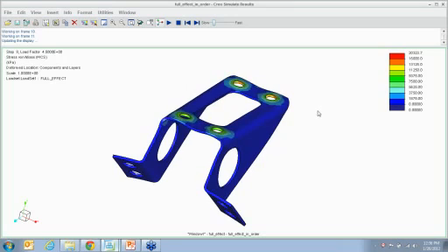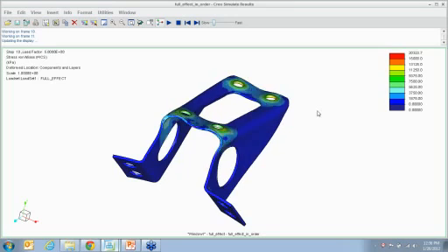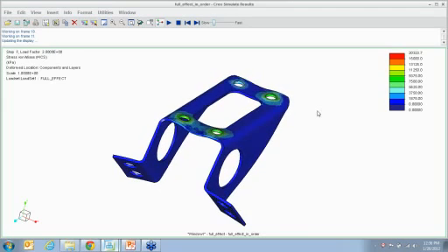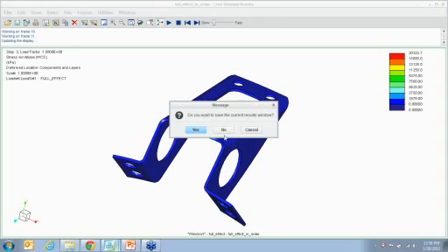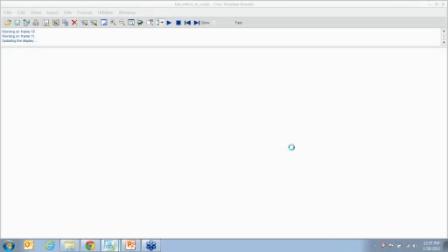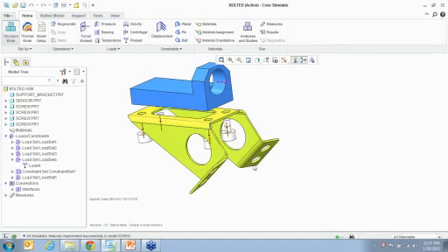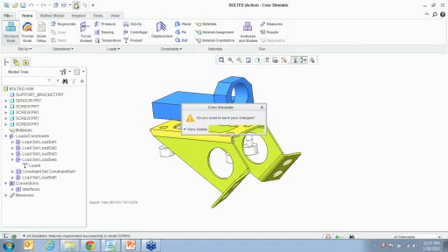So what it gives you is you can control during an analysis if the load runs from the start to the end of it, or does it start 2 seconds after the analysis and end 2 seconds before the analysis ends. So you can control the time through which the load is acting in an analysis, which gives you a much more realistic representation of what's happening in real life, right? So a couple of enhancements here that we can look through.